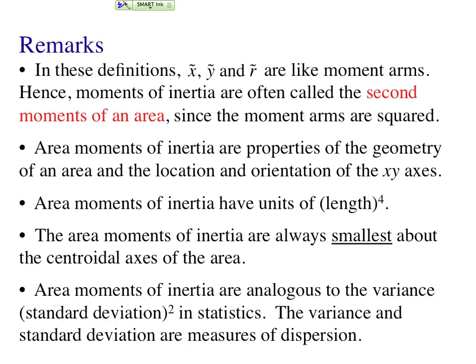Before doing any other calculations, we can get some insight into a basic structural element used in construction, the I-beam. What we want in construction is a structural element that minimizes its own weight and offers the greatest possible stiffness to bending, so we don't get sagging floors or parking ramps. In our previous expression for curvature, the area moment of inertia appeared in the denominator.